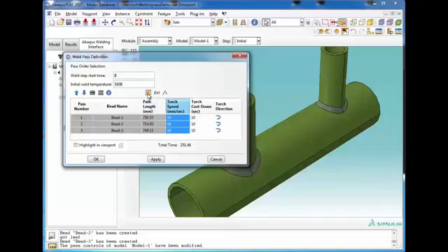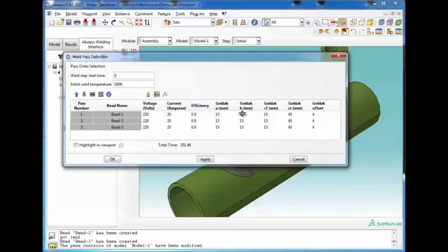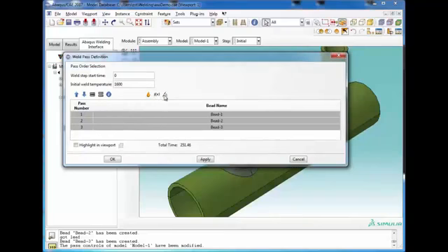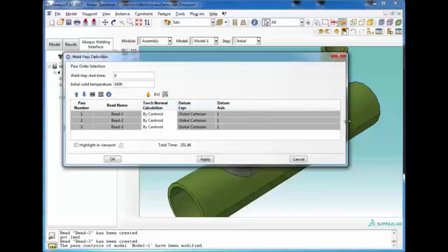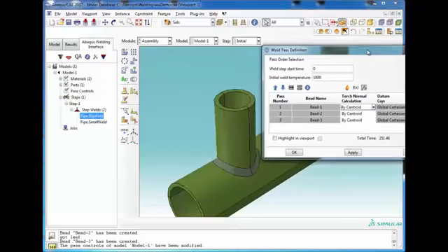All right, so what we're showing now is the torch movement controls. We can hide that and then display the Goldak parameters. Again, we can change any of these. And then finally we can display the parameters for defining the torch direction. The difficulty with using the Goldak flux is that it is dependent on the orientation, so you do have to define an orientation. We've put some automated methods in there for doing that: by centroid, by adjacent faces, and by a datum coordinate system. All right, so let's take a look at what those do.